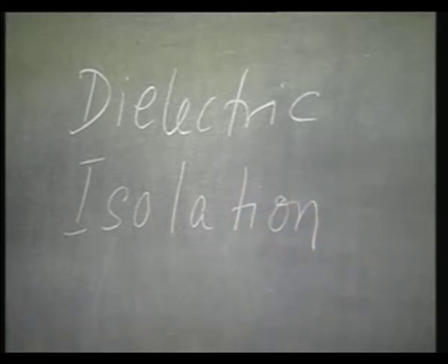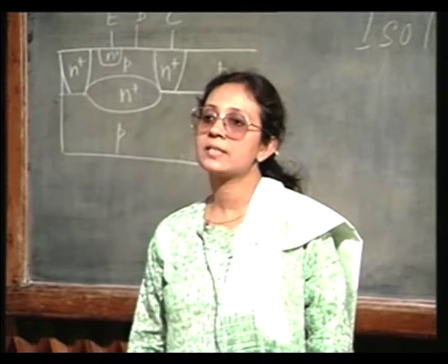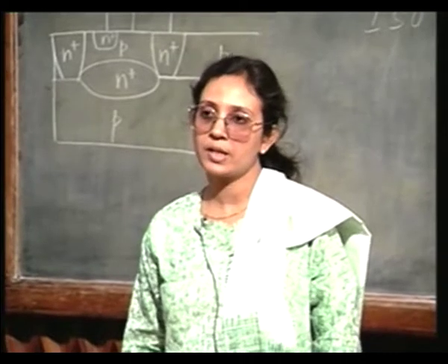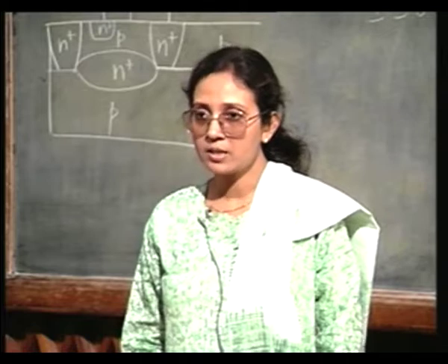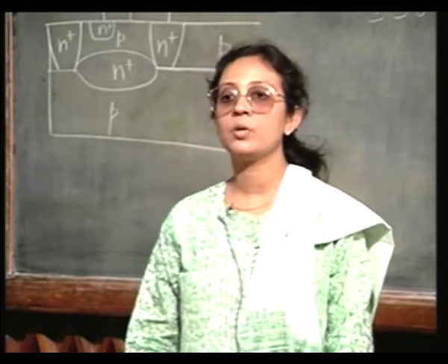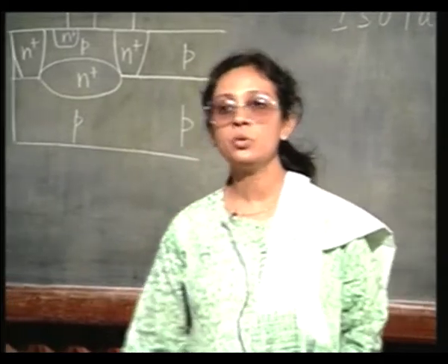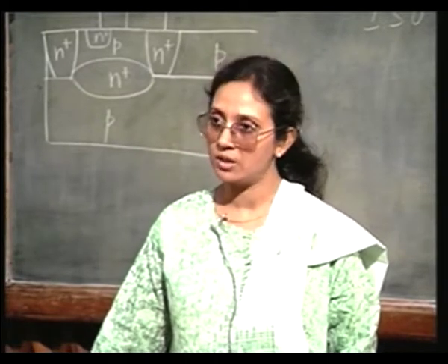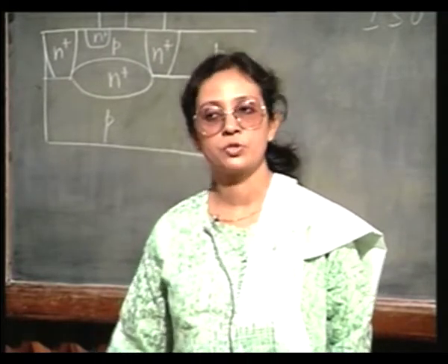Let me again remind you some properties of silicon crystal. Remember that we can get anisotropic etches which will etch preferentially. That is, most anisotropic etches do not etch one direction, they will etch all other planes. So, if you have a 100 substrate and you subject it to an anisotropic etch, you will have V grooves etched in it. Remember? Let us see whether this can be used.